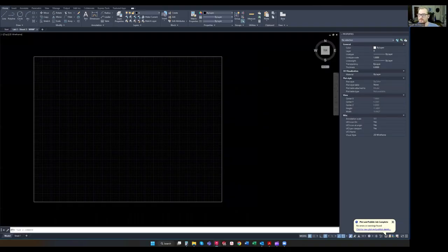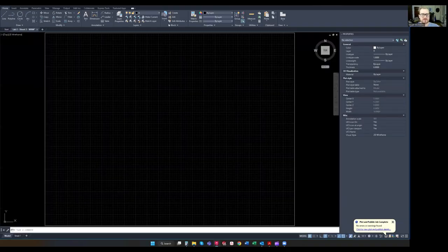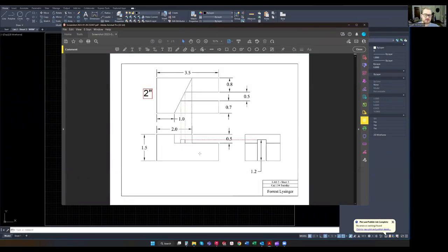And let's get started. So looking at the assignment sheet for this, I actually like to do some pre-work on stuff like this. For example, we don't have this dimension here, but if it's not given in the top view, and you draw a reference line straight down, you see that we actually do have that dimension. It's 2 inches. Also, the dimensions for this little box right here, we don't have those. But in fact, we know the height of that little box is 1.2 inches from the base of the part. And while we don't have these dimensions yet, we will have them soon enough.